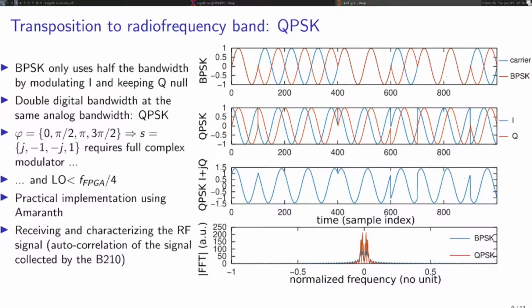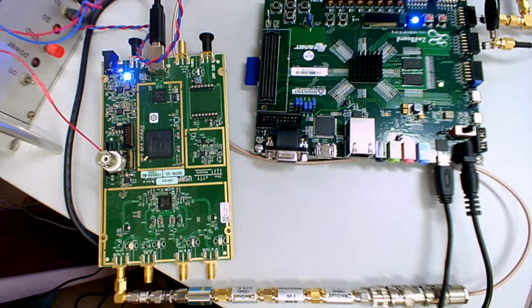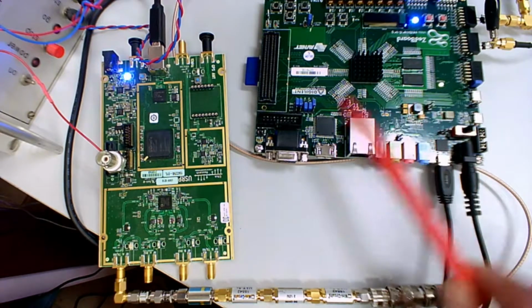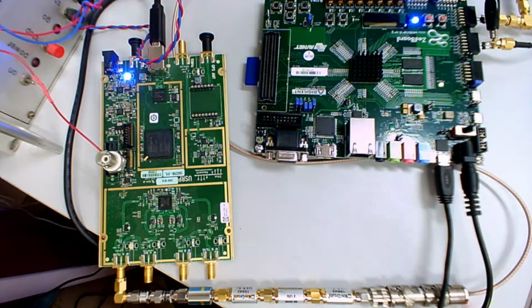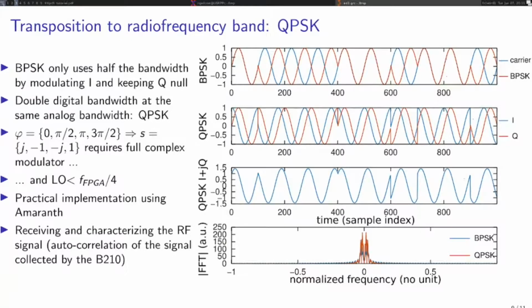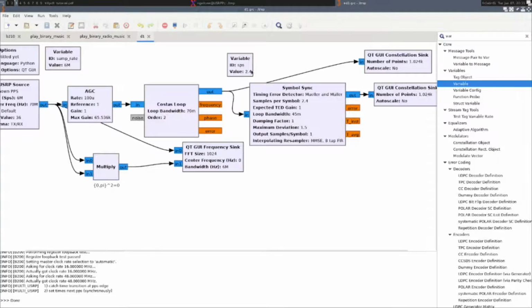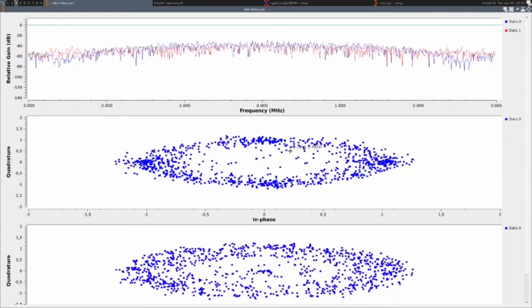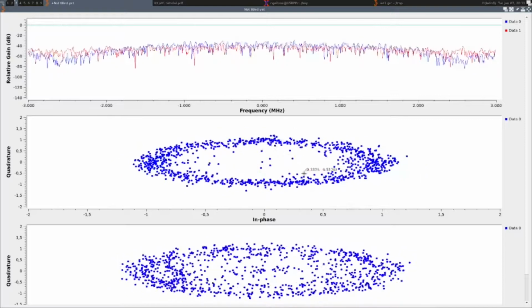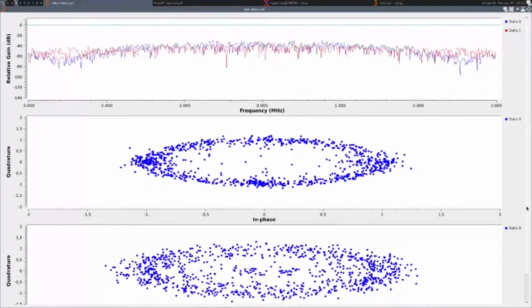So the FPGA has now been flashed with a bitstream. Again, same view. We have here the FPGA, and we have the same issue of these 2 clocks not being the same. So now we're familiar with the issue in terms of BPSK, but let's see what this means in terms of QPSK. So if we go back to our previous flowchart and just run it as it is, since it is configured for BPSK, of course that's not going to work for QPSK, and the synchronization is not occurring, so that we see the constellation rotating constantly. The Costas loop is unable to lock.